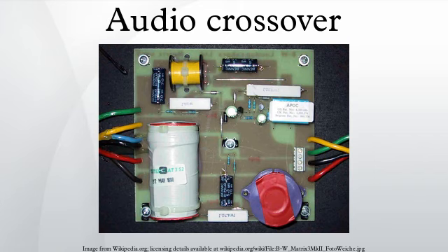Overview. The definition of an ideal audio crossover changes relative to the task at hand. If the separate bands are to be mixed back together again, then the ideal audio crossover would split the incoming audio signal into separate bands that do not overlap or interact and which result in an output signal unchanged in frequency, relative levels, and phase response. This ideal performance can only be approximated. How to implement the best approximation is a matter of lively debate.